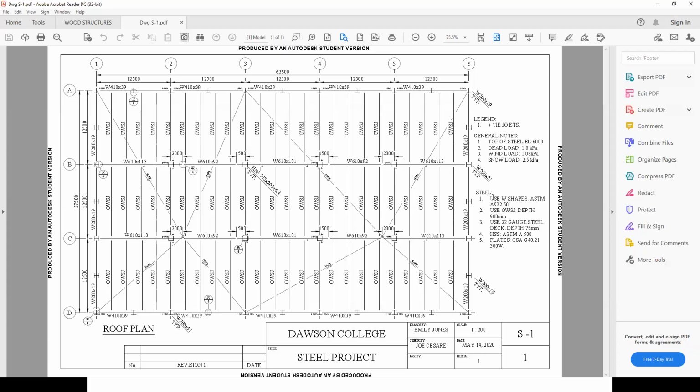I do recommend that when you're specifying your steel, you keep them all together. So this is the steel that we're going to be using for the HSSs. This is the steel we're going to be using for the plates and so on. So here is where you put your general notes. And of course, you always give your loads, because it's the fabricator of the joist and the deck that's going to decide based on what you show here. And of course, we're going to talk about wind load, and you're going to have to show your wind load. Then the manufacturer knows how he's going to have to design his joist for what loads.